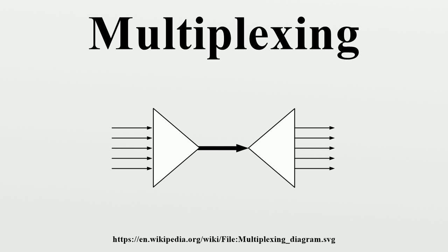Code division multiplexing. Code division multiple access, or spread spectrum, is a class of techniques where several channels simultaneously share the same frequency spectrum, and this spectral bandwidth is much higher than the bitrate or symbol rate. One form is frequency hopping, another is direct sequence spread spectrum. In the latter case, each channel transmits its bits as a coded channel-specific sequence of pulses called chips. The number of chips per bit, or chips per symbol, is the spreading factor.